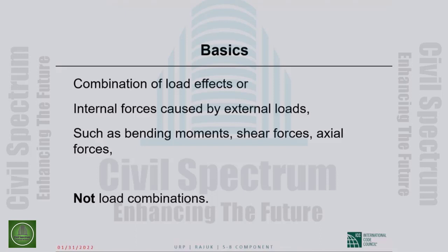When we talk about load combinations, we are really talking about combination of load effects, combination of internal forces caused by external loads, such as bending moments, shear forces, axial forces. So these so-called load combinations are not load combinations at all. That's extremely important, that you absolutely must remember the rest of your professional life.